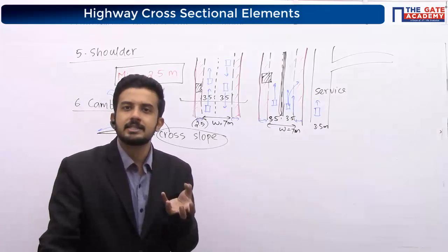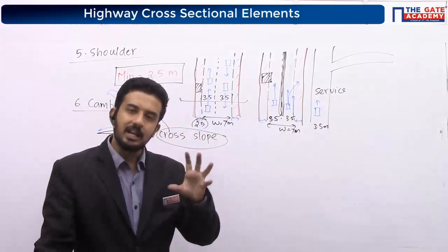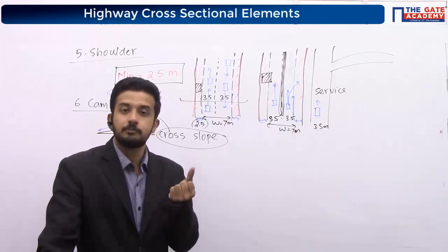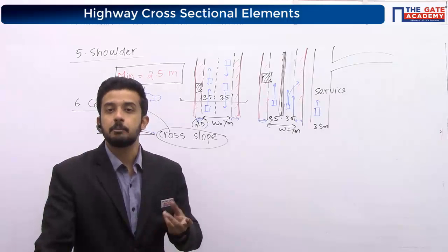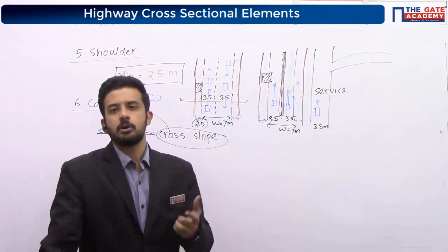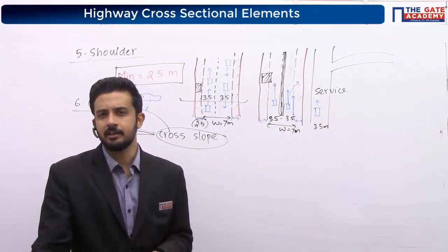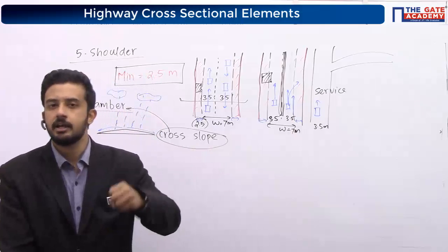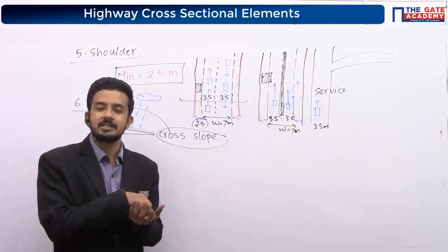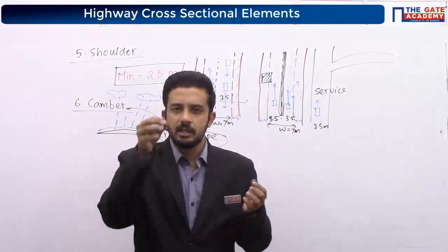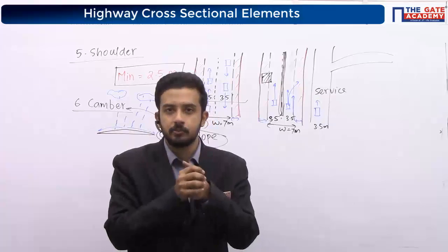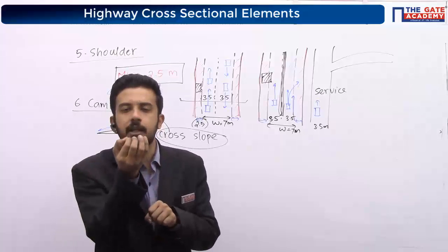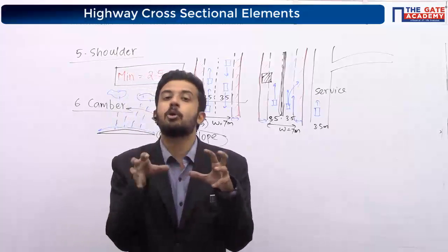Also, if the water is getting accumulated, it will affect the bonding between the coarse aggregate, fine aggregate, bitumen and all. You might have studied potholes and all in your classes. Potholes, then raveling, rutting, lot of things are there. Some distress, failures will happen. Some gutters may start forming on the road. If some water is getting accumulated, it will slightly penetrate. There will be some slight voids on the surface. Alligator cracking, very good. It will penetrate through the voids and affect the bonding.